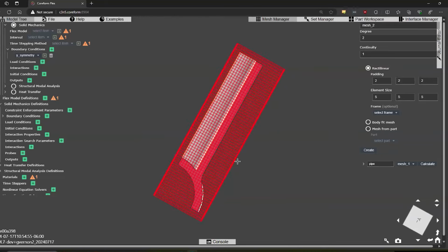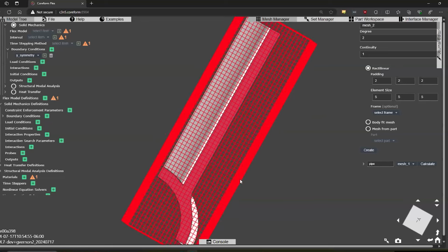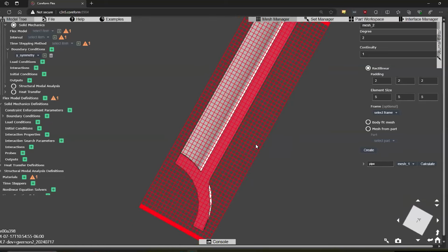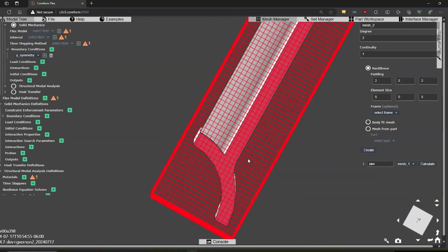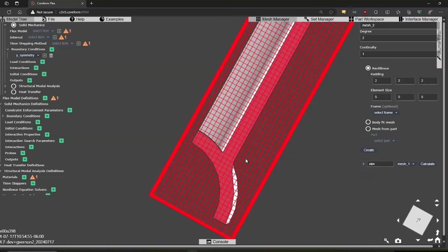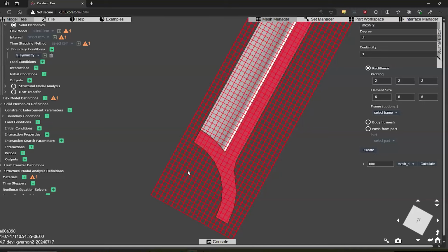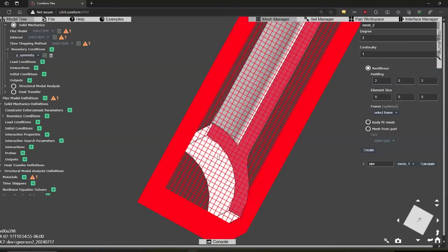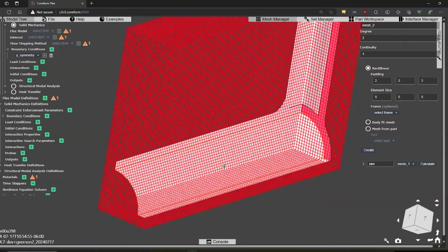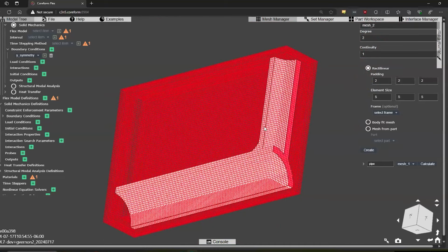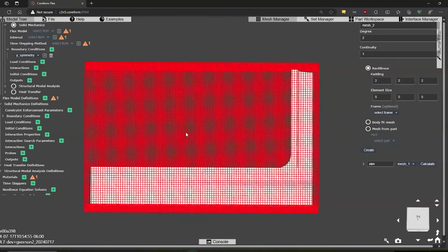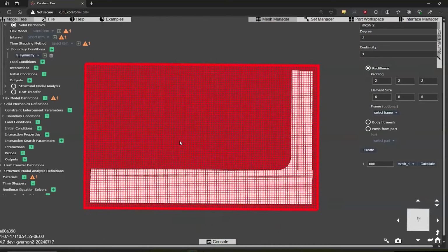We didn't talk about it today, but we've been doing a lot of experimentation where we've seen that the traditional rules of thumb of having, say, 4 elements or a thickness are really quite overkill for a lot of these problems. But you can see that this mesh does not align with our geometry, and it doesn't have an effect on our accuracy. That's all that meshing has been relegated to now, to choose an element size. And as we get more mature, even choosing your element sizes will be an afterthought.